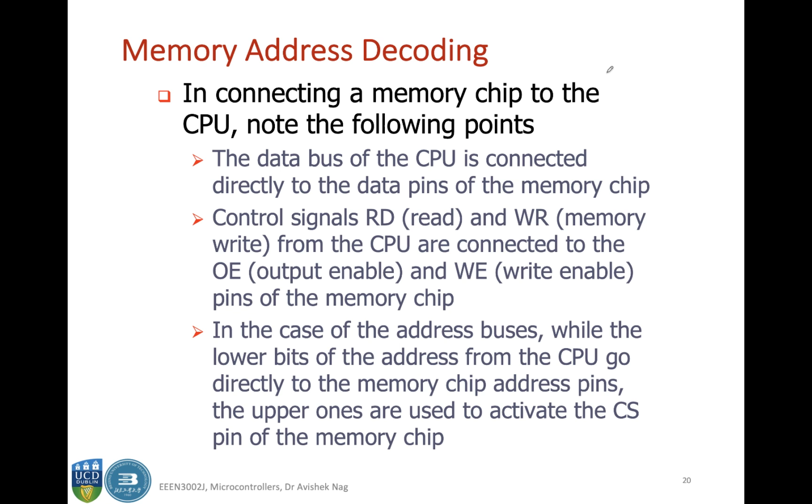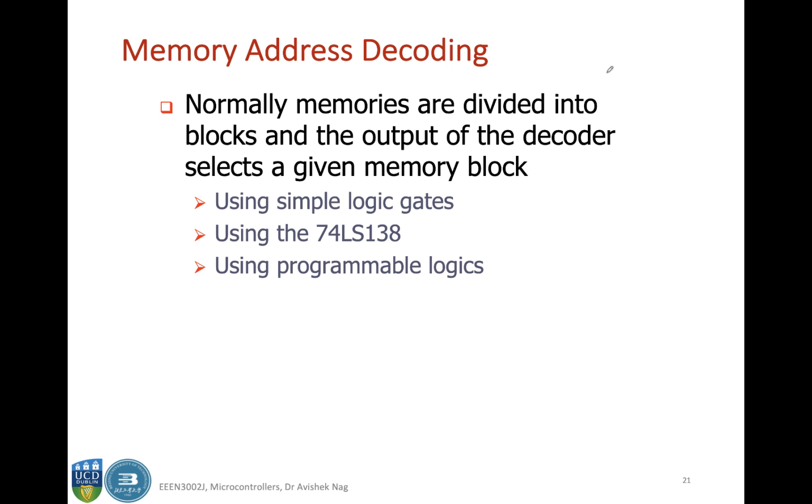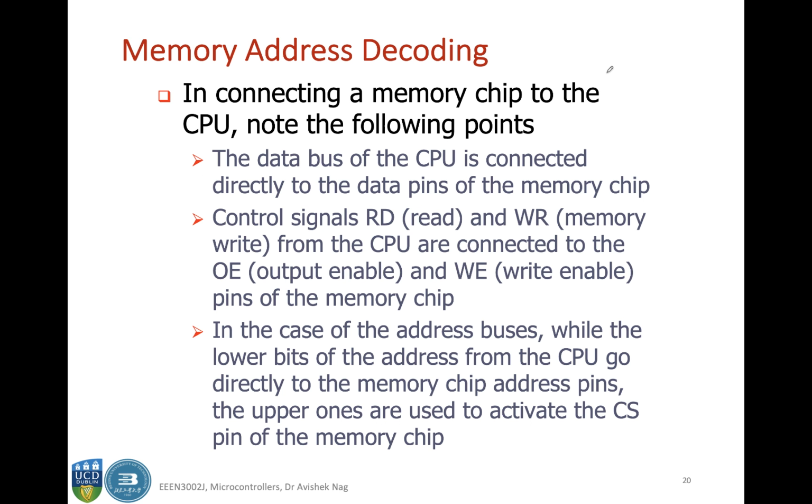This is the high-level arrangement. Normally the memories are divided into blocks, and the output of the decoder selects a given memory block. While interfacing your microcontroller with an external memory, these are the different arrangements. The data bus goes to the data pins of the memory.